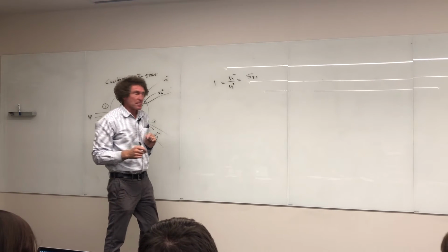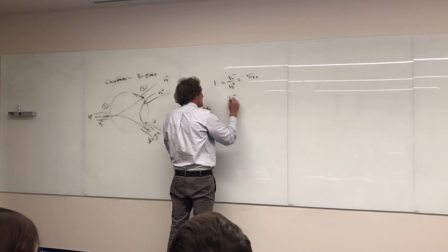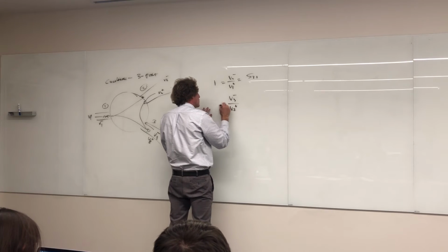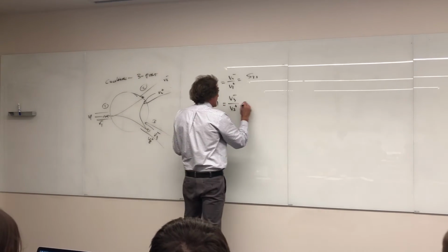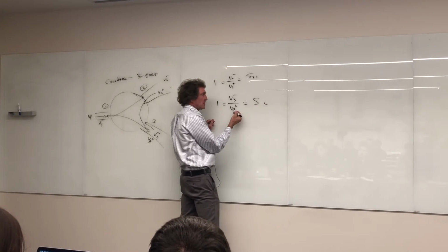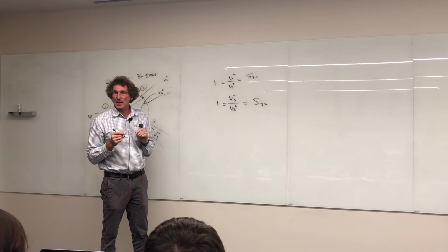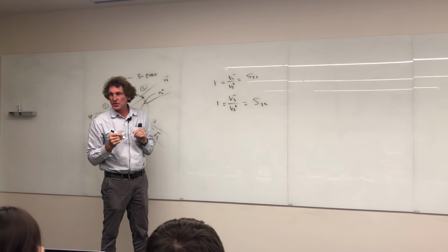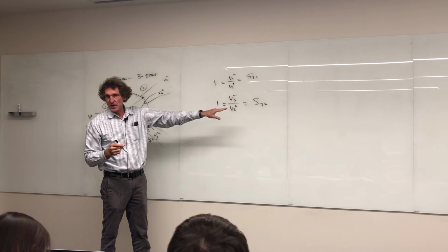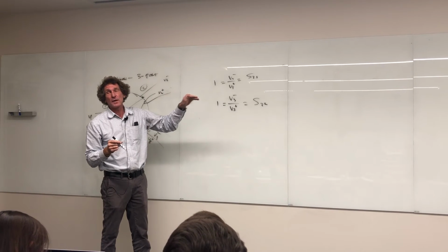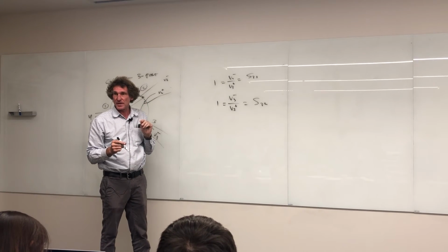What else do we have? We have V3 minus over V2 plus equal 1, correct? Well, what is that? That's S, 2's coming in, 3's coming out. Correct, class? S32. Do you follow me on this, guys? Make sure you do, because you have to understand the way I'm creating this matrix. This is an ideal matrix. We're saying everything coming in port 1 comes out port 2. Therefore, this ratio is 1 without any phase delay.